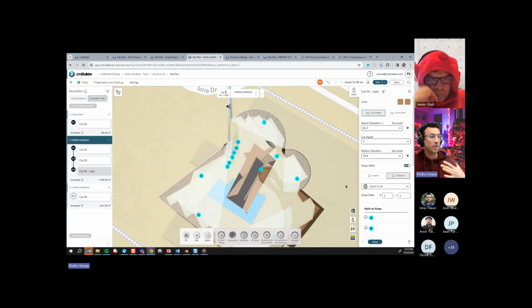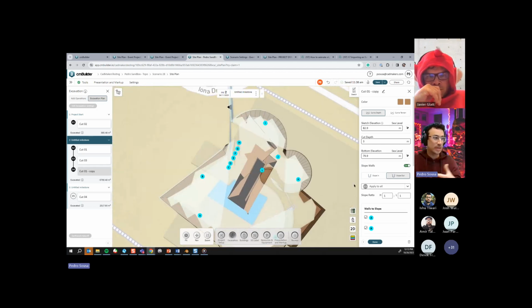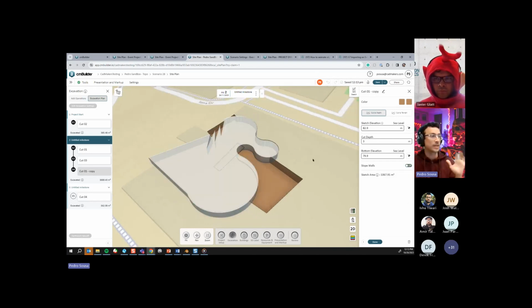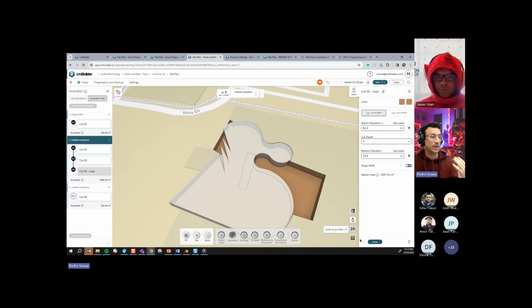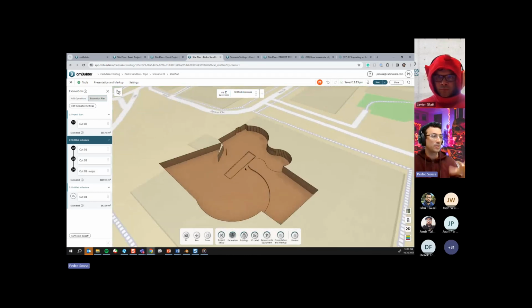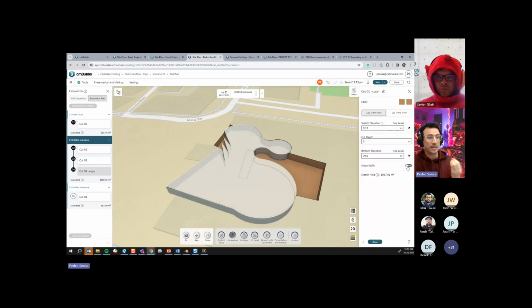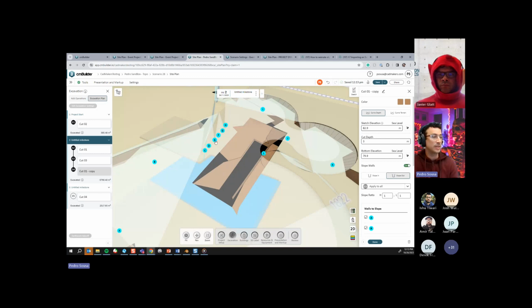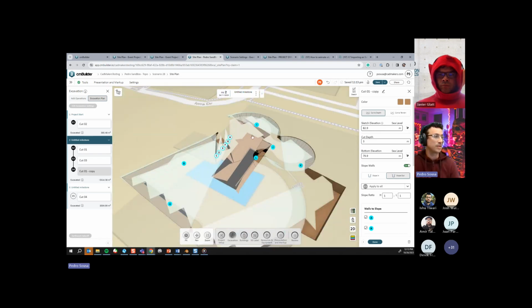And this really looks like a problem of intersecting slopes. So when you have a geometry that creates several intersecting slopes, this might be the case. One way to figure out if the slopes are the problem is just to turn them off. And then you can see, okay, if my geometry that was created over here does not have any problems or any broken shapes, it means that the slopes are the problem. So you can just go in and start deactivating some of these, so you can visualize which slope is causing your problem. Cool, because every time you deactivate these slopes, you're going to get a partial result of that geometry.